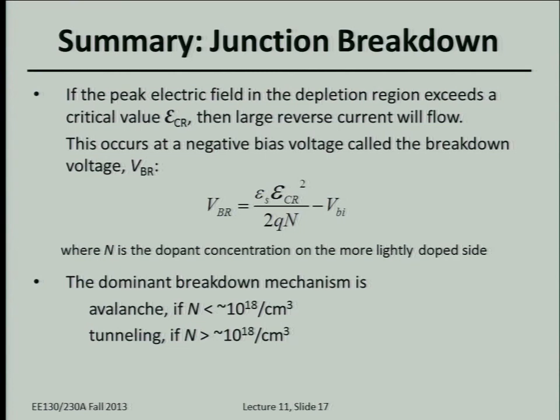So that's what's happening with so-called band-to-band tunneling. Right? You're tunneling from an allowed energy state in a valence band. That means a covalently bonded electron. The electric field is so high that when you apply this reverse bias voltage, you can actually just rip an electron directly out of the covalent bond. You don't need any avalanche or absorption of light or thermal energy to allow the electron to escape. Okay, so that's the physical picture of what's going on with quantum mechanical tunneling breakdown.